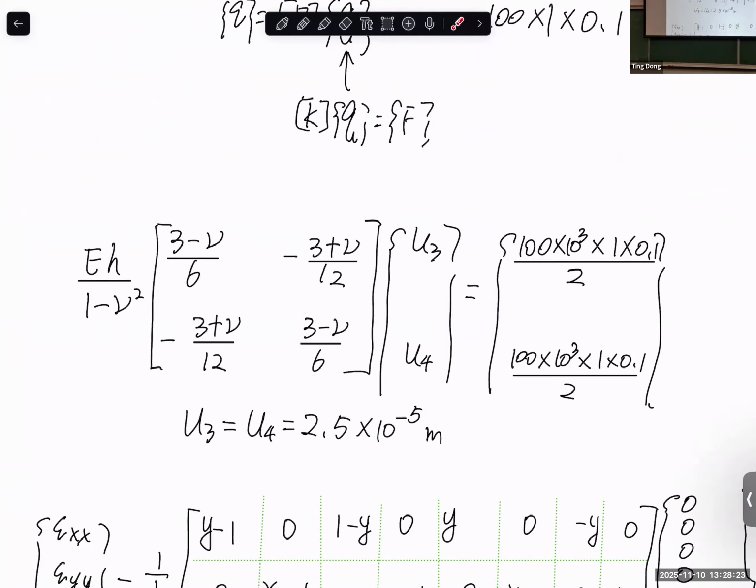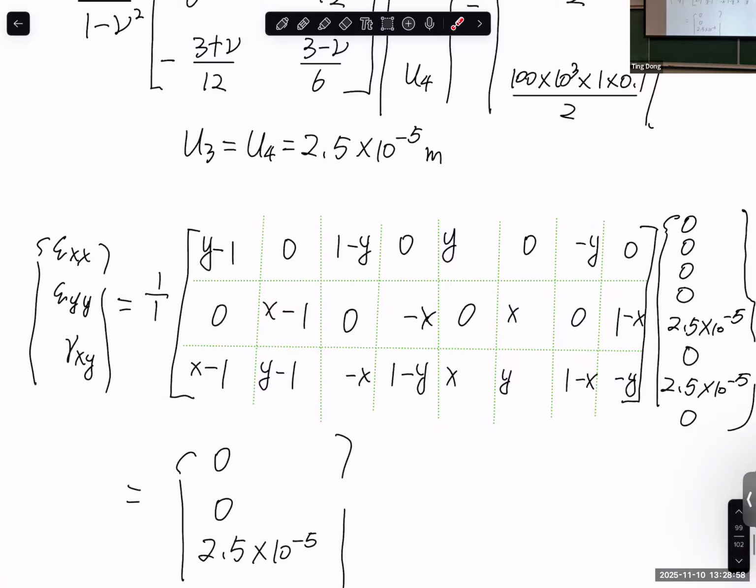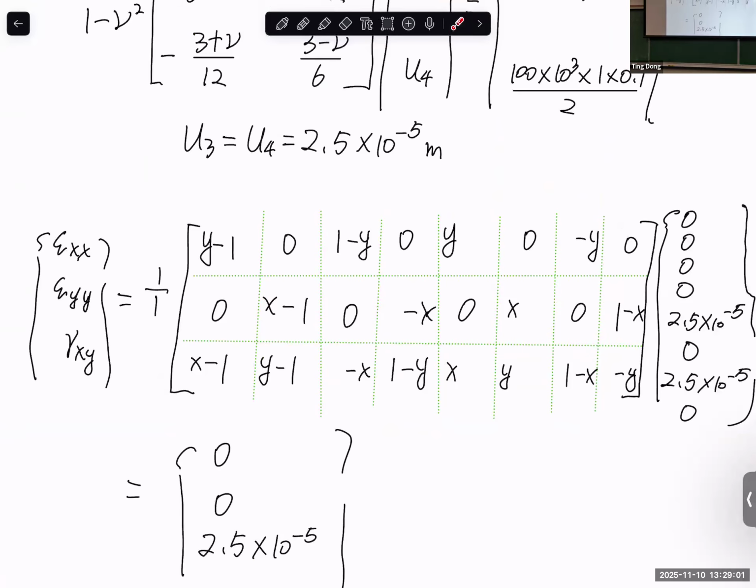For this situation, as I explained, because it is a simple shear, there's only one non-zero stress component or one non-zero strain component, which is a shear strain or shear stress. So no matter whether you use CST element, which is capable of representing constant stress, or use a more advanced element, Q4, it can have the variable X and Y in the stress or strain. It will still be constant because the original stress in the structure is constant, right? So it's the same. That's why I didn't go one more step to stress, because that part is just repetition. So we are done with this.